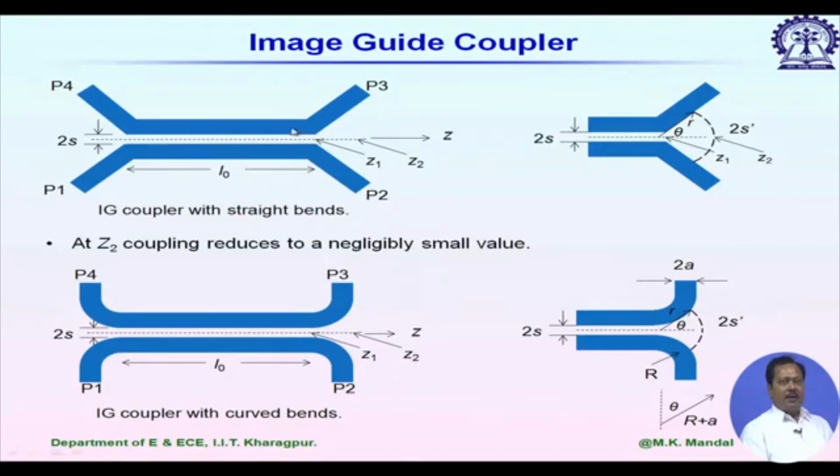Now, for practical realization, as I said, whenever we design any bend, we have to be very careful. Each and every bend is associated with some reactance, and at lower microwave frequencies usually we do not consider its effect, as it is negligibly small. But if we go for high frequency design, typically above 60 gigahertz, we have to consider their effect. So, you can use any full wave simulator to characterize and to minimize this reactive loading effect.